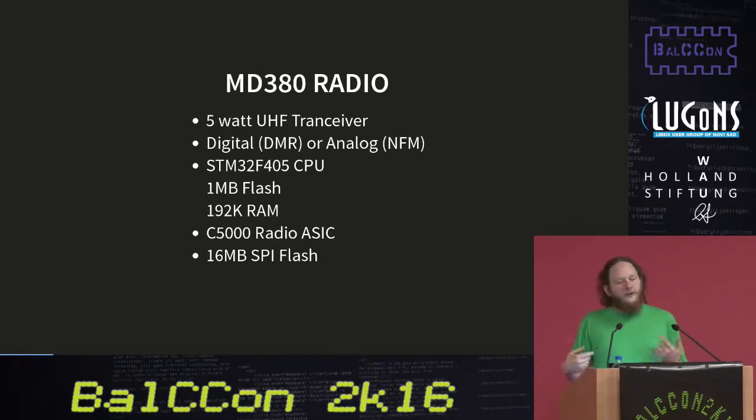And you sort of give it either your audio frame or your data frame during the time when it's not transmitting, and then in the other half of the time it does the transmission. And the opposite on reception. But you're always using that idle time. And this way you can have two conversations running at once, but the radio is only able to participate in one of them. So you're not going to get stereo sound or be able to transmit and receive in the same conversation at the same time. So you have to physically push the button to transmit and release it to receive.